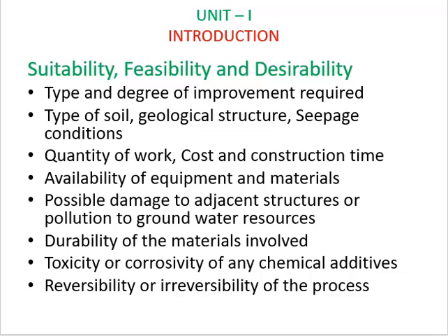Next point is durability of the materials involved. Before selecting the chemical agents or grouting materials or geosynthetics for the ground improvement, the durability of these materials have to be assessed with respect to their long-term efficiency. If the chemicals selected are not durable, they may leach out from the site during the rainy season.